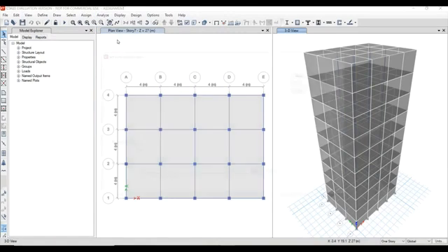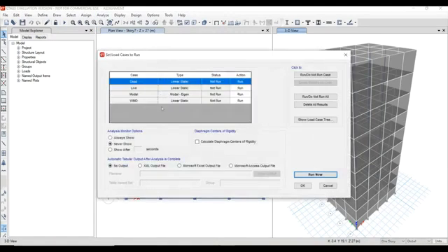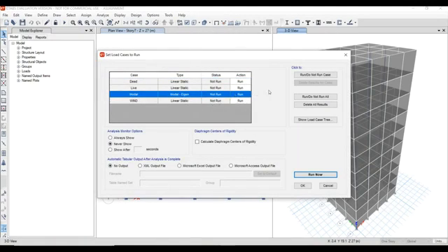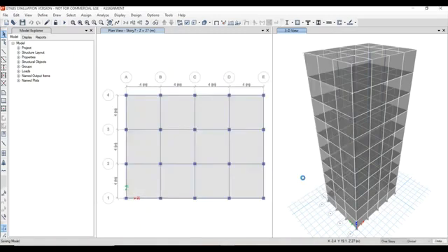After selecting the load combination, now we need to analyze. Go to analysis, set load cases to run. For the time purpose, let us skip the analysis of modal load case. So click on run or do not run case so that the modal analysis will not be run. So let us run for dead load, live load, and wind load. And click run now. And you can see the bottom left corner the progress of the analysis.